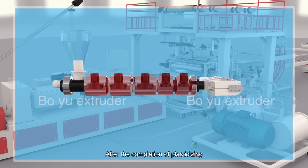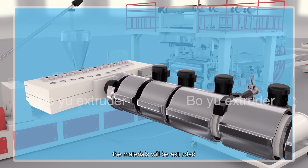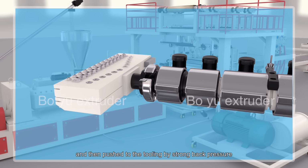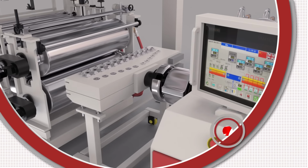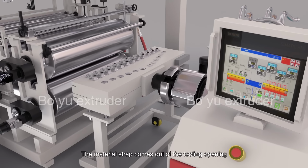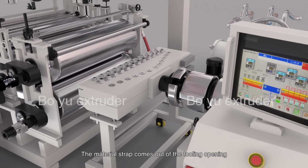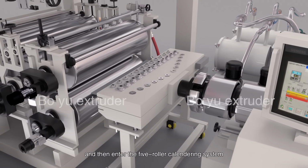After the completion of plasticizing, the materials will be extruded and then pushed to the tooling by strong back pressure. The tooling size is determined by product specifications. Calendering system. The material strip comes out of the tooling opening and then enters the 5-roller calendering system.